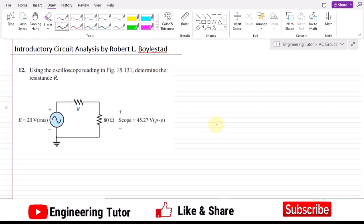So this is question number 12 of our book, and in this circuit we are given a very simple series configuration of two resistors in which the source voltage is known, which is the RMS value, and similarly the oscilloscope is also connected across this 80 ohm resistor, and from it we have seen that the calculated peak to peak voltage is 45.27 volts.